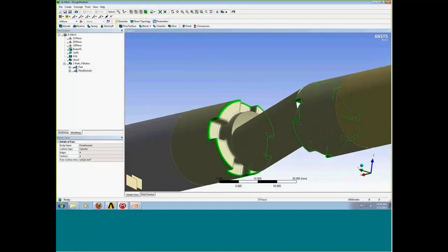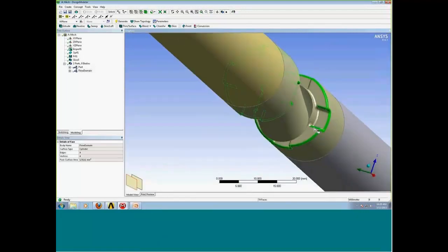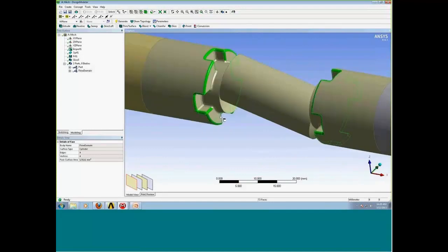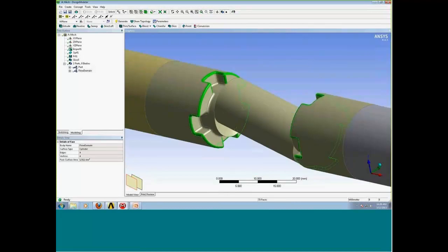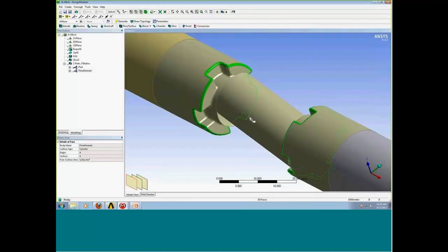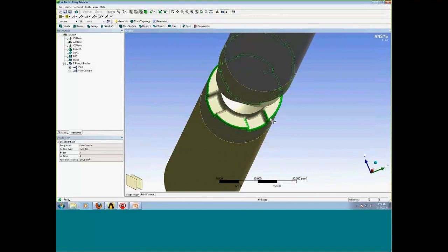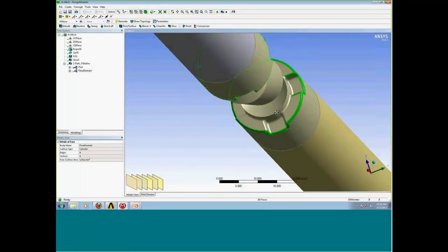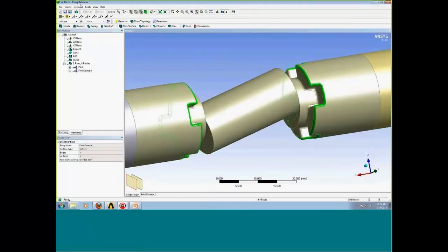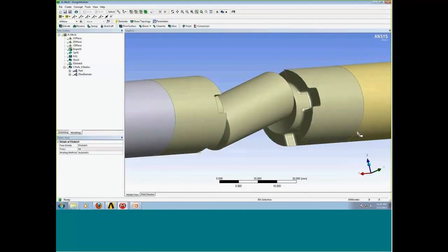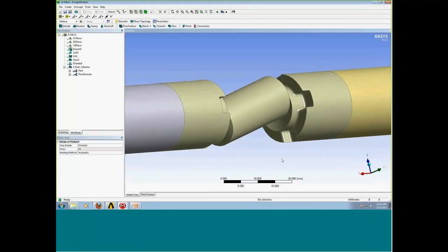So let me just quickly unselect these faces here, so that when I go ahead and use my face delete operation, I will only capture the fillets on the outer radius, and so that'll rid me of those details. But maybe I want to keep the vertical fillets. So let me go to the Create menu, do a face delete, and if we take a look at what this is going to do, I go ahead and generate that, and you see it just gets rid of those fillets there. So a really useful tool.